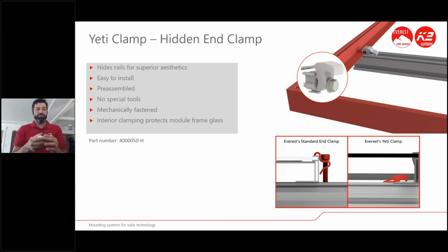the module. So what I usually do is run one side with the module flush to the rail. Everybody corners out their array when you're doing chalk marks and measurements, and you know where your array is going to start. So I would put the rail either flush to it or leave a little play out if you want to chop it at the end, or you can start it there and then run the rails all the way out and then not cut anything. You can even land all your modules, and then the last module you lay down, you can stick this underneath, lay the module down, mark it, bring the module up, chop it to that mark, bring it down, and then it's perfectly flush with the array.